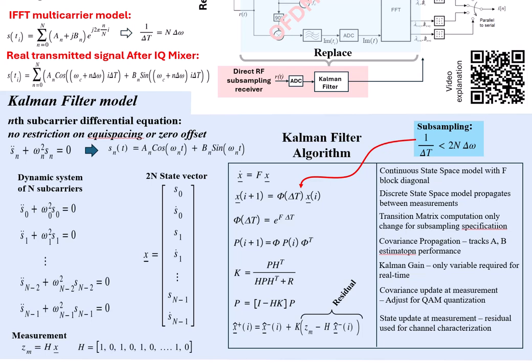Because of the frequency normalization to 1 and the use of carrier cycles to replace time, all computations can be performed using fixed point arithmetic. Also note that the sample interval, or delta t in cycles, enters only in the computation of the transition matrix. The delta t will be less than 1 cycle for sampling faster than the carrier frequency, or may be greater than 1 cycle for subsampling. For the simulation case studies below, we will use a sample interval of 10.2 carrier cycles.